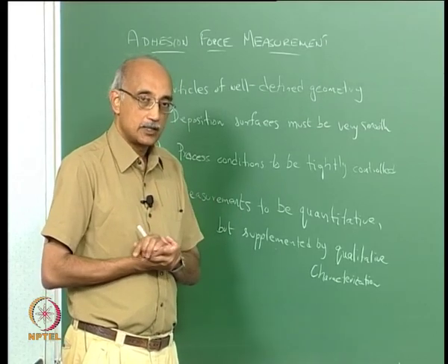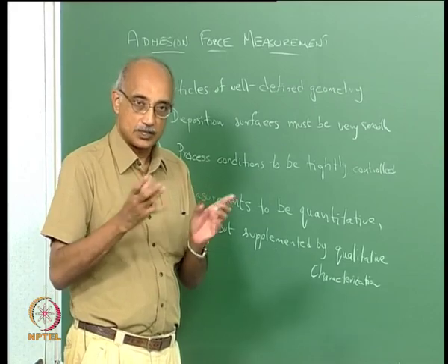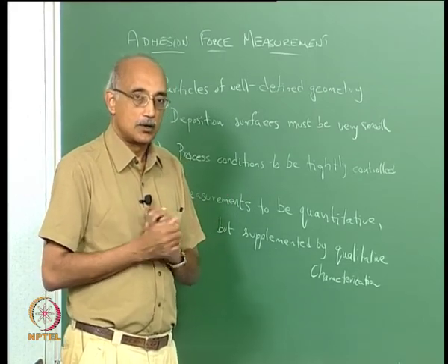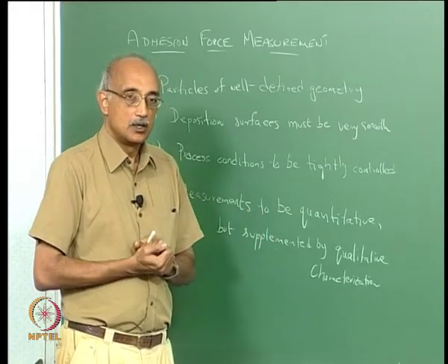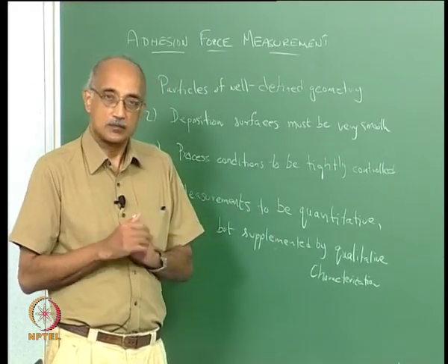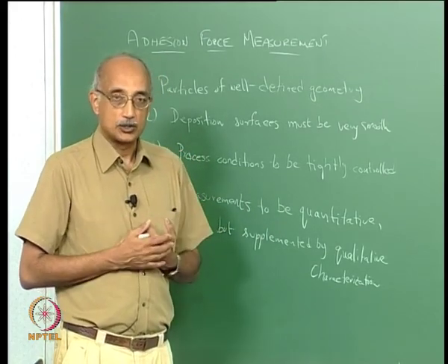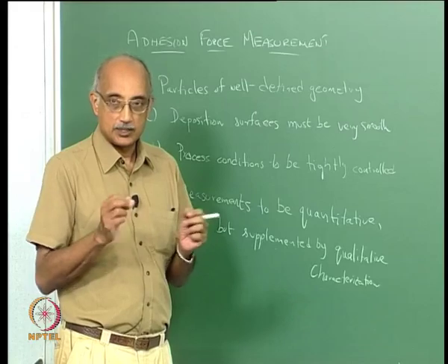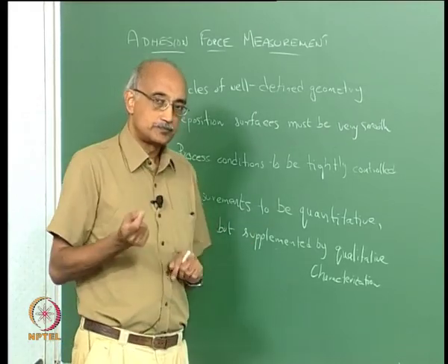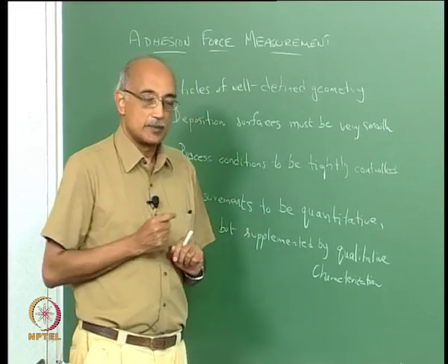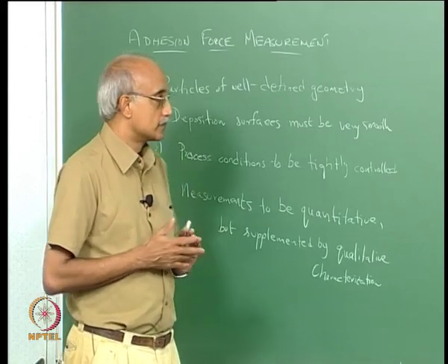Make sure that what you are counting as a particle is really a particle and not just a feature of the surface or material that is part of the surface which has broken off, or a simple hole in the surface, because all of these can fool a particle size analyzer or even a particle counter into thinking that these are particles. So it's very important to be open to doing auxiliary measurements that can confirm your quantitative data.